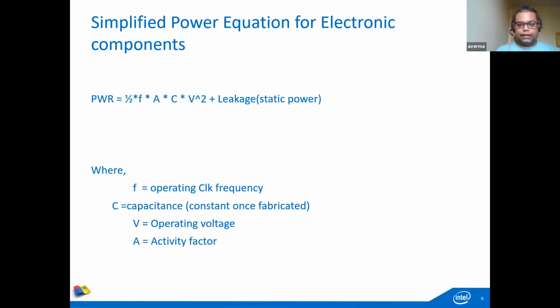Now in certain conditions, in the first equation, we are talking about the activity factor here. Think about it: if your system is not active, it can go into the power gate state. In the power gate state, the connection of these circuits to the supply can be disconnected, because they do not need to work at that point of time.